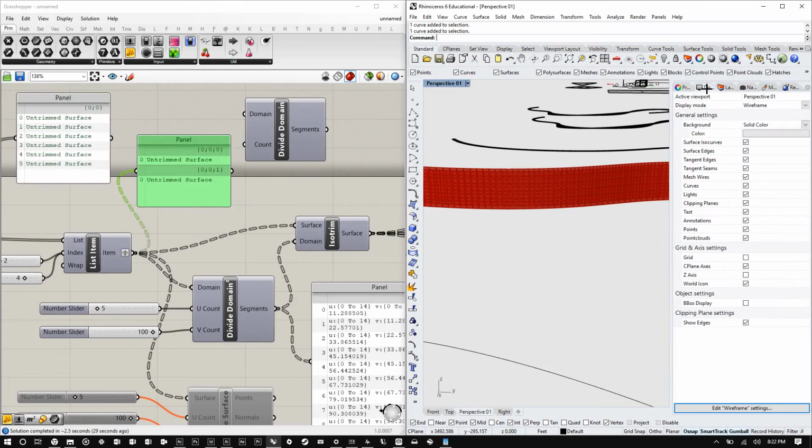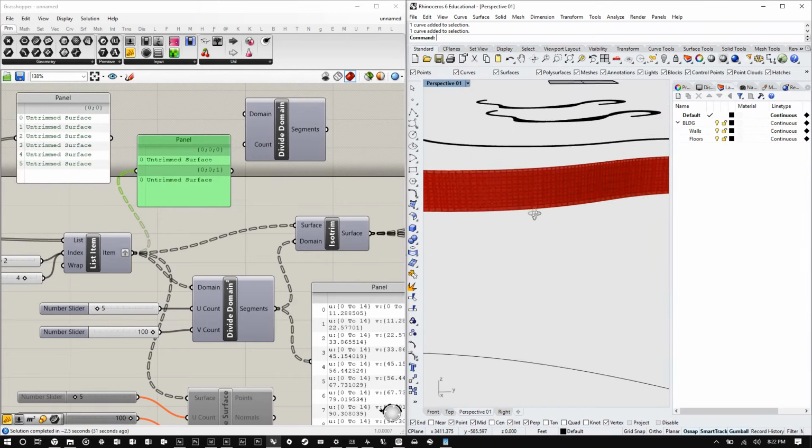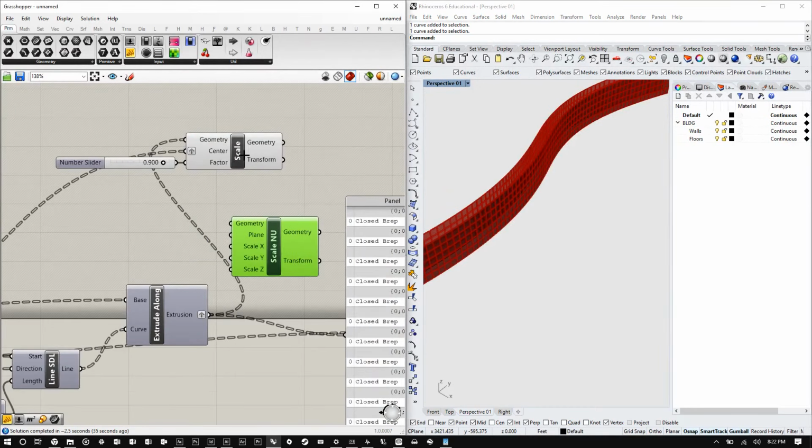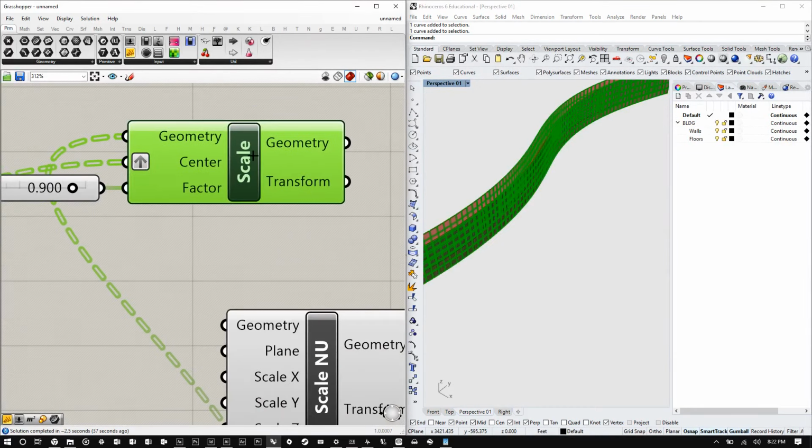Let's say I wanted to get to a stopping point and see what these looked like in Rhino. I'll then do what's called a bake. So I'm going to grab this one that houses my tiles. I'm going to go create some layers here because I'm going to bake them to a specific layer. I'm going to create a master layer called wall, and some sublayers. I'm going to create tiles, and I'm going to create another one called base.